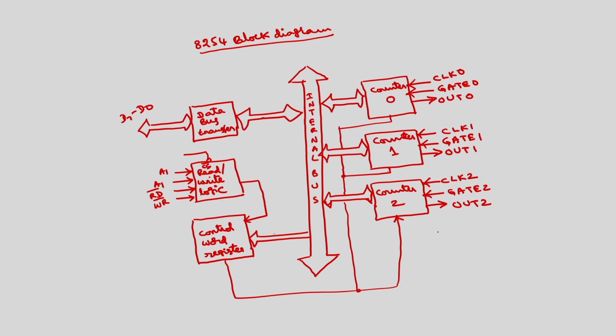Now, here you can program this. There are 3 16-bit counters. We can count using BCD count or binary counting. And you can program this as timers also. The timers can operate in 5 modes. I will explain each mode in detail.